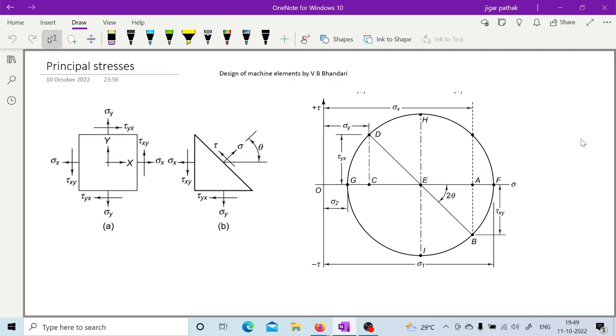Sorry, can you please repeat? We were focusing on the rivets, that's why we take the shear yield stress as the failure stress, and if you're considering the sheet, whether we consider the failure stress as the shear stress.